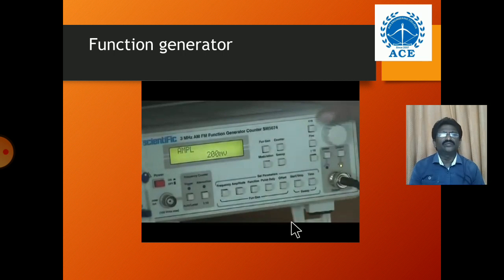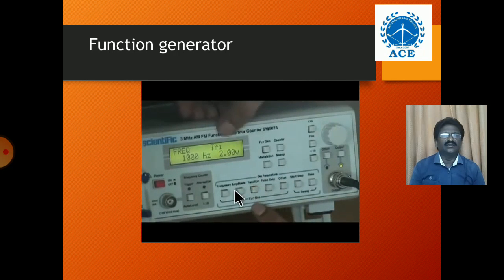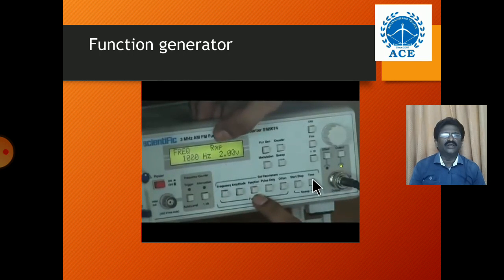Now let us come back to volts when I press this times 10. When I press this times 10 one more time, you see the point here can be moved to set values according to our requirement. So right now, based on the operation, it is 2 volts with a frequency of 1 hertz. In the same way we can change the frequency with the frequency factors. These are the representation of the frequency values according to our requirement.